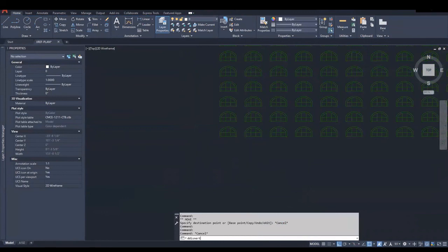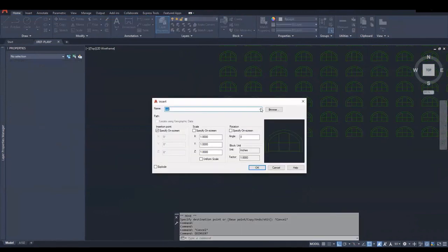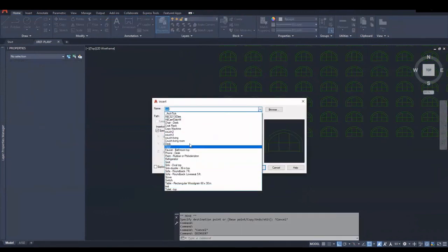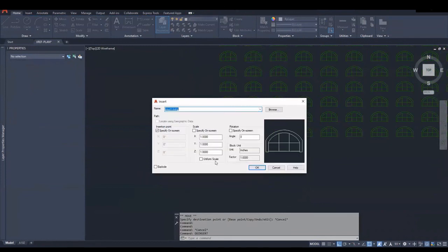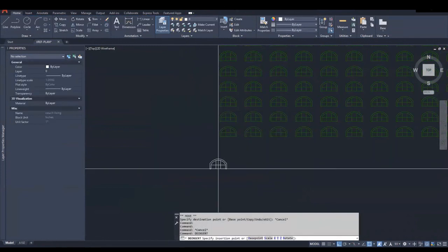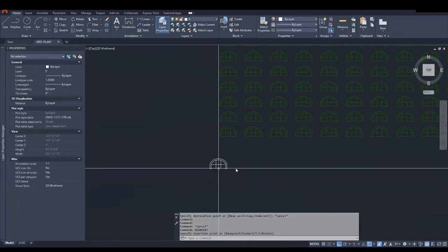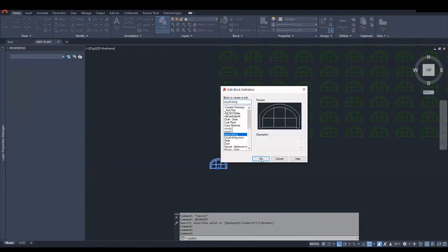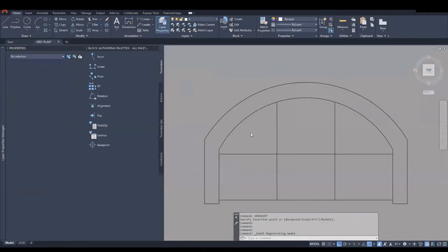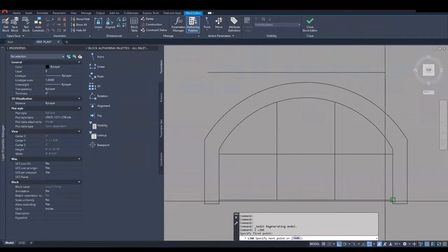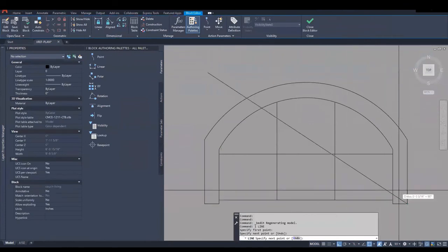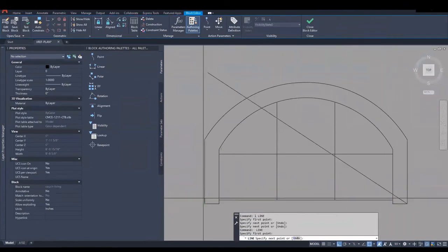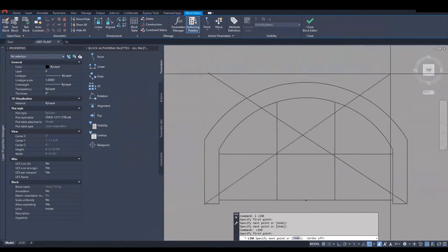And obviously, if we had a stadium of 5,000 seats and I wanted to change the way the seat looks, you're not copying 5,000, 10,000, whatever copies of that chair all over the place, right? It's an array. I could redefine the block just like I did before, and it will change all 5,000, 10,000 seats all at once, which obviously is a huge, huge time saver.